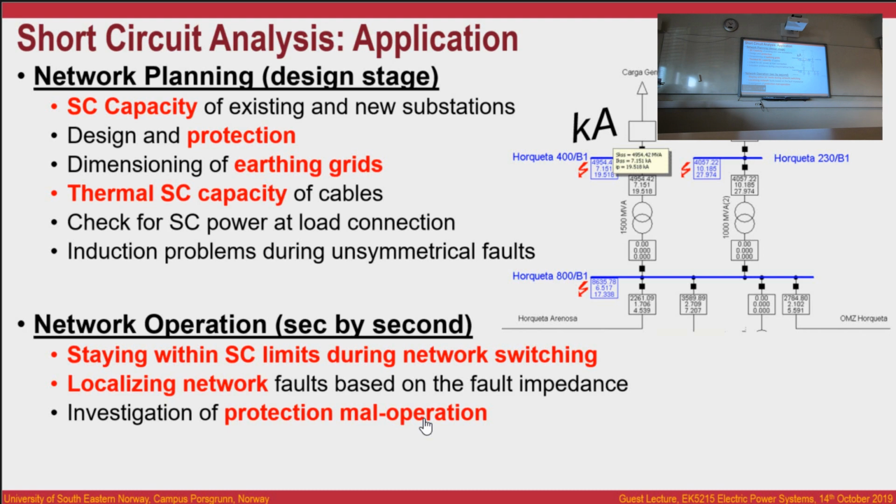Protections, believe it or not, are control systems. In control systems, you have measurements, and from the measurements you take decisions. The decision here is very simple, but very expensive. This guy is sitting, taking measurements of current. Okay, there is no fault. If the current goes above a threshold, oh, this is a fault, open the circuit breaker. That is the job of one protection.